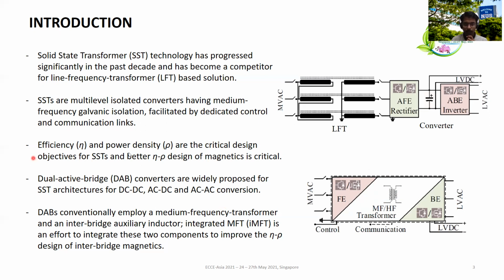The efficiency eta and power density rho are the critical design objectives for solid state transformers, and for superior designs in terms of efficiency and power density, a good design of the interbridge magnetics is quite critical.